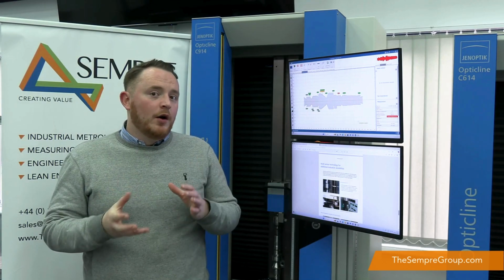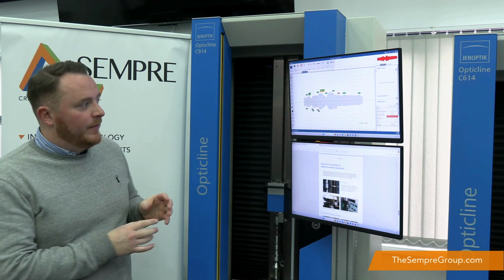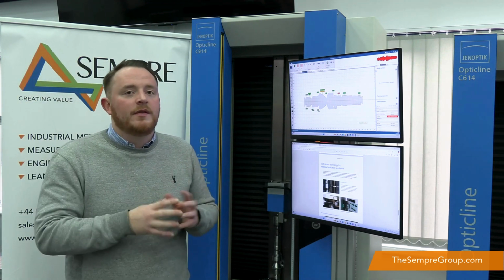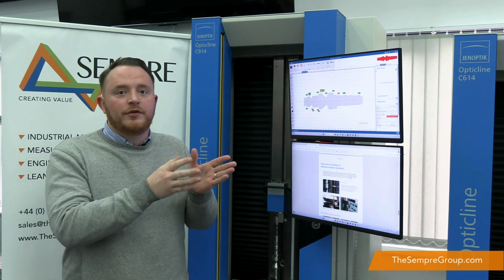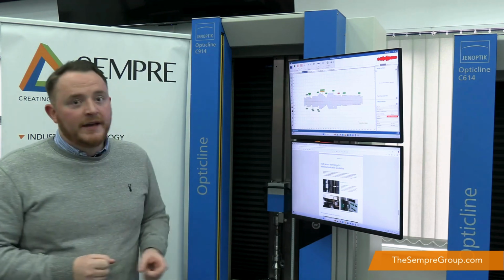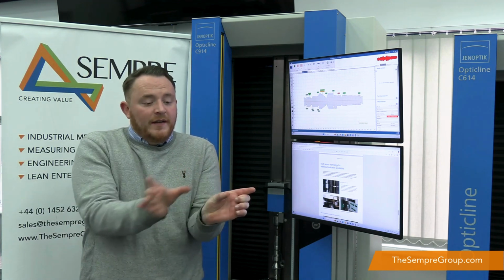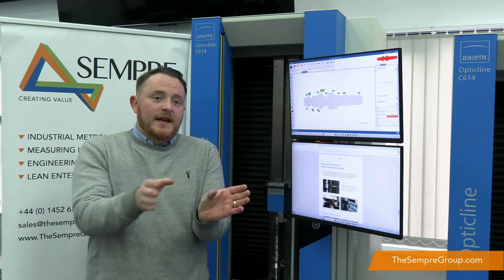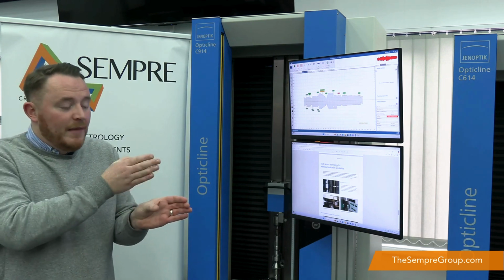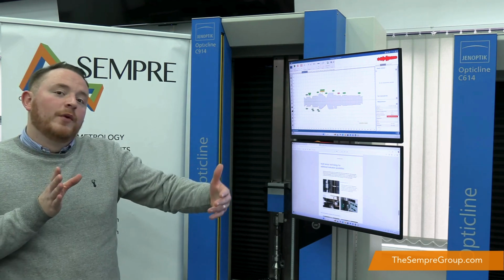So now we're taking a look at the optimization techniques that we can use within the software. The Opticline system, as opposed to some of our competitors within this field, will use multiple objectives. The idea behind that is that we can keep the resolution as we go to larger diameters. So this 1.4 system here, effectively we have a 50mm camera, we have another one above it, and then another one to the side of that. And what that does is that creates an overlap so that we get our 140mm diameter, but we maintain resolution from a 1mm measurement all the way up to 140mm.